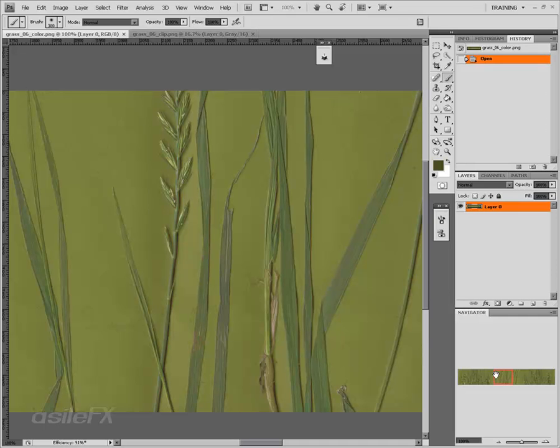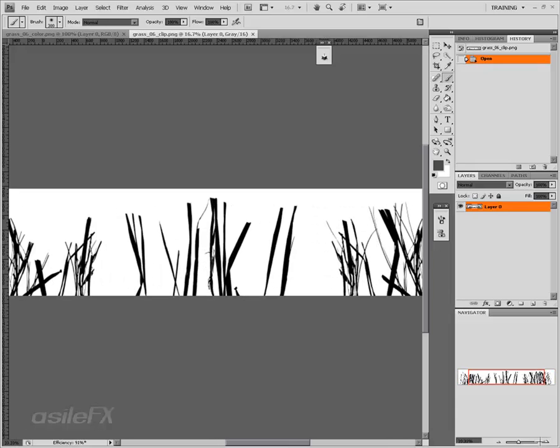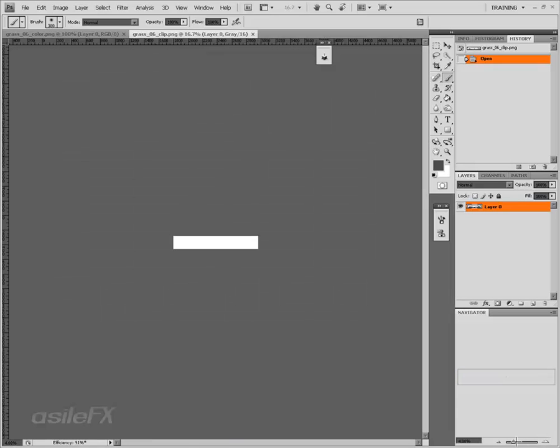But it's really important that you don't have that red background left, because with MIP mapping and resampling of images as you're moving through your scenery, what can happen with the rescaling and resampling is it can pull out some of those colors, especially if you have a little bit of an inaccurate transparency map. Now this is a modified transparency map where I cut off the tips to make it more of an even type grass.